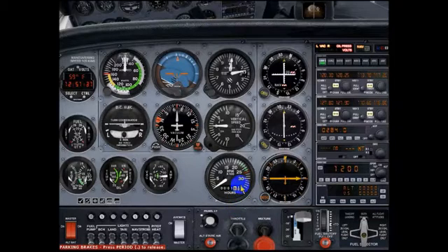Placarding. Alright, now, just to talk a little bit about placarding. Now, in the POH, in most Cessna POHs, it will give you maneuvering speeds. When an aircraft panel is placarded, meaning there's a notice, that's what a placard is. It's a card of notice. For this airplane, the maneuvering speed is 105 knots. This would probably be at the highest weight, and you would consult the pilot operating handbook to give you an idea of, if we are at lighter weights, what the new maneuvering speed would be.